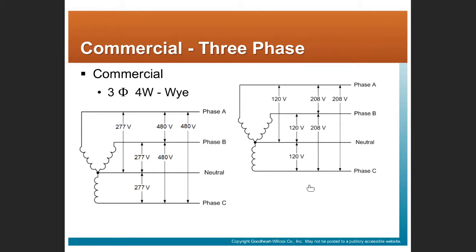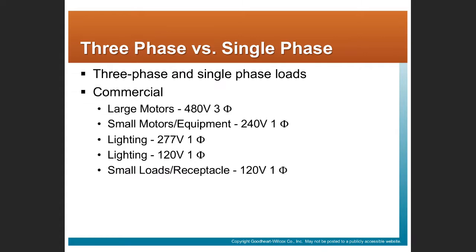Here's examples of commercial wiring details. Three-phase, I think in Delhi was a 120/208 system. So we saw certain loads in Delhi, like the lighting loads would be 120. The rooftops, so 120 line to neutral, 208 line to line, right? So we saw, I think the rooftops at Delhi were 208 volt three-phase. So again, in the same wiring system in a commercial building, we can have both single phase and three-phase loads together in the same system, depending on how it's wired.